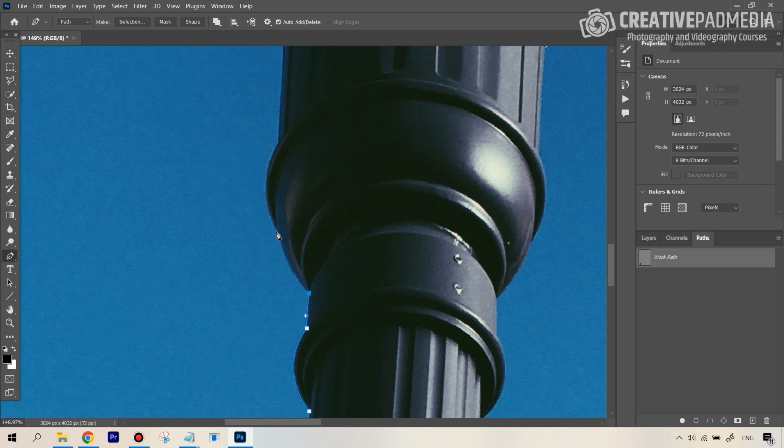So now we can follow the same path. We can go to the end of this curve, hold down, and can you see? Now it's not a problem. But now, again, we're going to face that same issue, okay? So the non-destructive way would be what? We're saying, listen, so that you don't cause any problems, I'm going to make you slightly shorter and change your angle to the actual angle on the subject like this. So you don't interfere with my next anchor point, which is going to come here, like this.